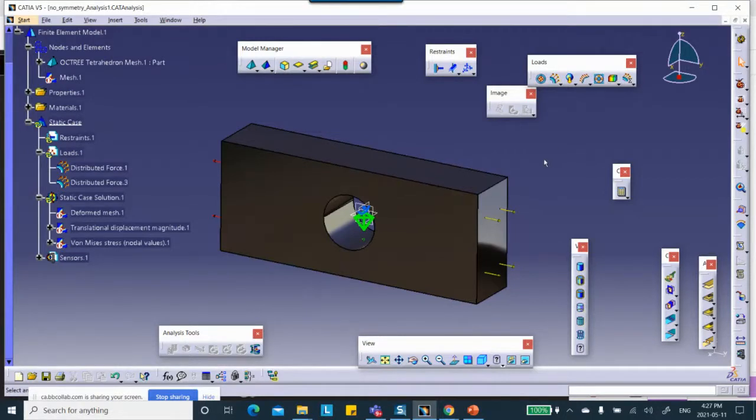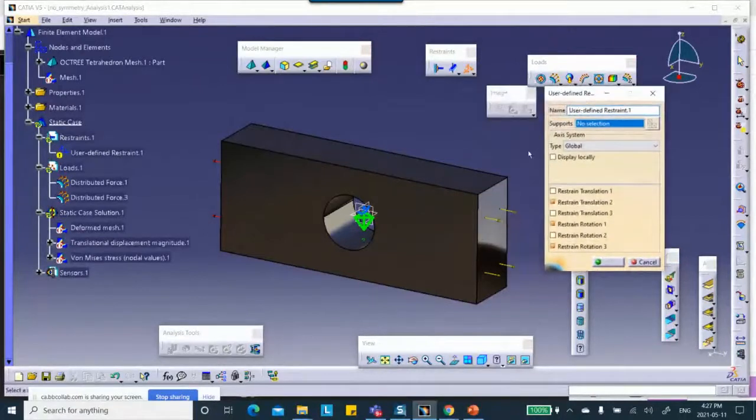Here's the way I'm going to fix this issue. But first of all, I don't want this thing to fly away, like I don't want it to be in the back of a truck, and the truck moving. So at this point, I want 3 displacements fixed. One way, of course, is to clamp it. Clamping means that point is fixed. But I'm not going to clamp it. I'm going to use this other icon here, which says enforced user-defined displacement. Okay. All right. So I'm going to take that corner point, and